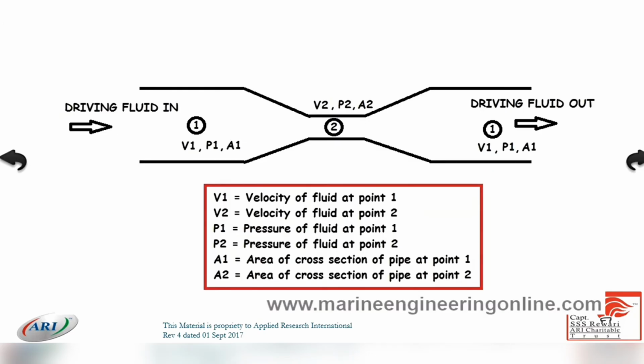So it's easy, there's no clingage, very little clingage in the tank. There's a free flow of oil. If you give a stern trim, oil is flowing easily, as there are no obstructions for the flow. And they have provided a well also on the after side of the tank. All the bell mouths, stripping bell mouths and the main bell mouths, are inside the well. You can literally make the tank dry, because the construction is giving an advantage to the ship, and in addition to that, you have an eductor system for stripping the tank. Very effective. You can literally make the tank dry.